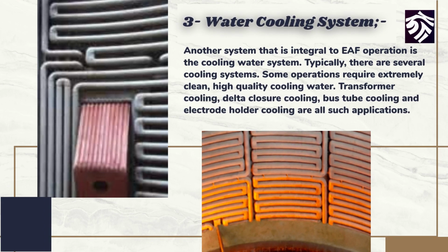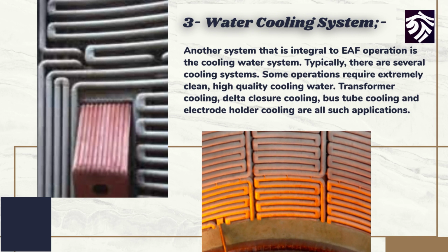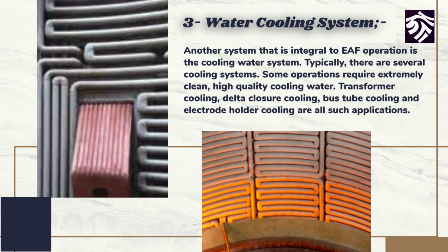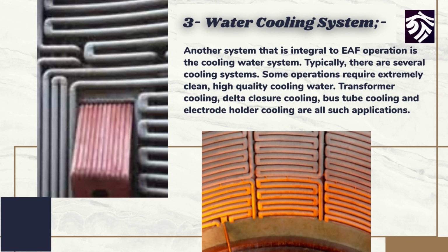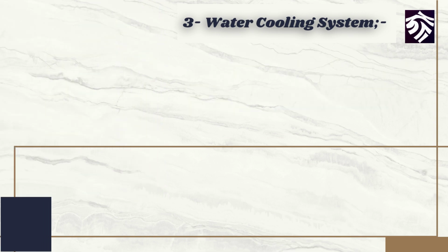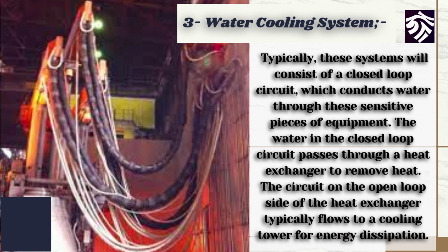Water cooling system. Another system that is integral to electric arc furnace operation is the cooling water system. Typically, there are several cooling systems. Some operations require extremely clean, high-quality cooling water. Transformer cooling, delta closure cooling, bus tube cooling, and electrode holder cooling are all such applications.